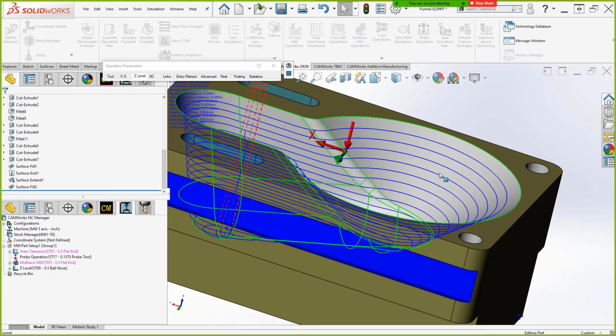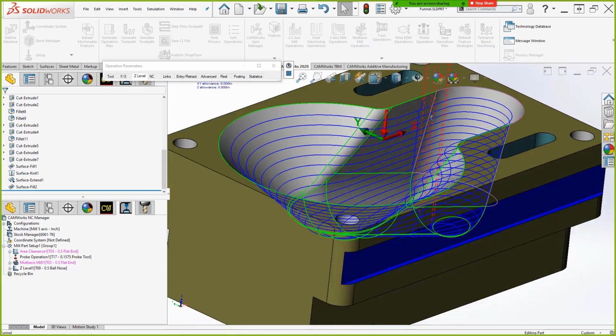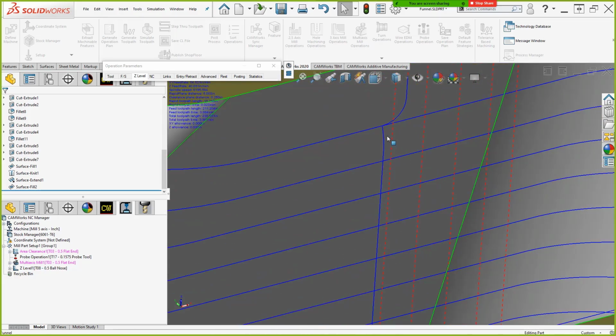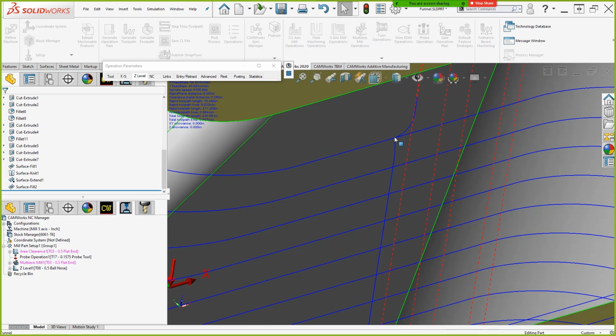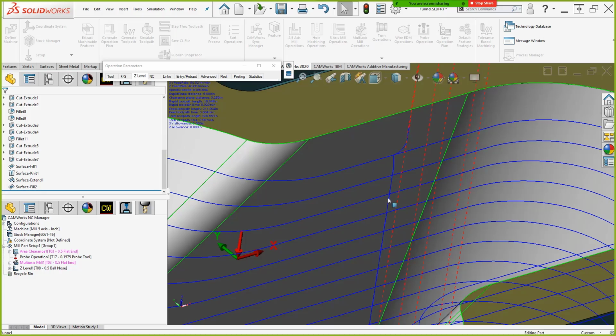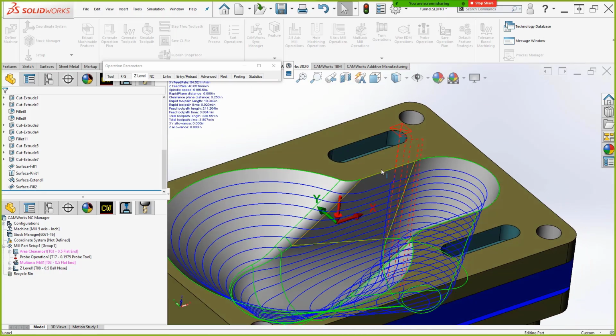Yeah, spaced out a little too much, but it looks good and all. There's great toolpath. It's very clean. But look at this transition, right? This transition between Z heights is kind of abrupt. It's literally 90 degrees. It's literally turned as turned it can be from the existing toolpath. If we're going to polish this later, it might not matter, but you still want to aim for a better surface finish in general and not have these awkward transitions.